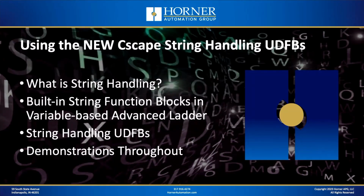Okay, so here's how we're breaking down the topic. We're going to start with, what is string handling? What do we mean by string handling? We're going to talk about the built-in function blocks that are in Cscape, variable-based advanced ladder, and then we're going to talk about the new string handling user-defined function blocks. What functions are built in? Which ones are we adding through these UDFBs? And of course, we'll have plenty of demonstrations throughout.